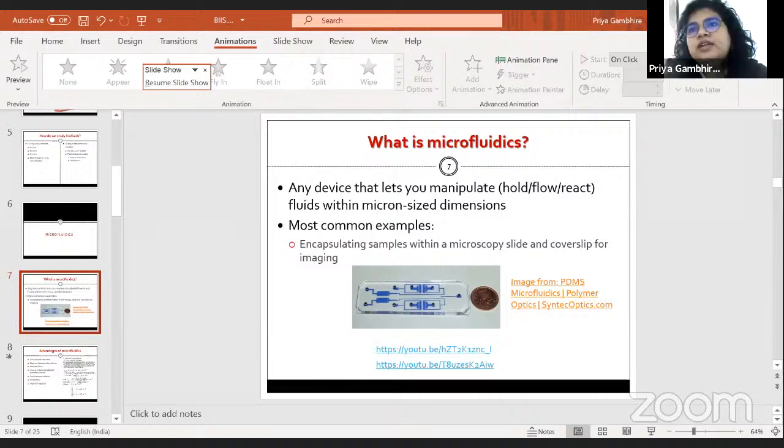So that you'll have to customize to your application. What I showed over here is to make a basic droplet. You can use the velocities of either of the channels to set the size of the central droplet. But once you form those droplets, you can test them for the concentration that you need, and then tweak the velocities of the other two channels to get a larger or smaller droplet.